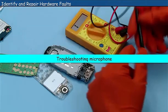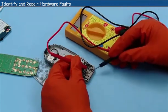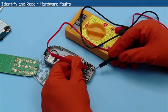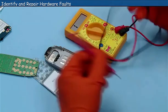Troubleshooting microphone. To test the microphone, take a multimeter and set it in ohms range. Connect the probe to the exact terminal of the microphone, that is, positive to positive terminal and negative to negative terminal. The multimeter has to show some value. If we interchange the terminal, it should not show any value. If the above criteria are satisfied, then the microphone is said to be in good condition. If not, replace the microphone with a new one.